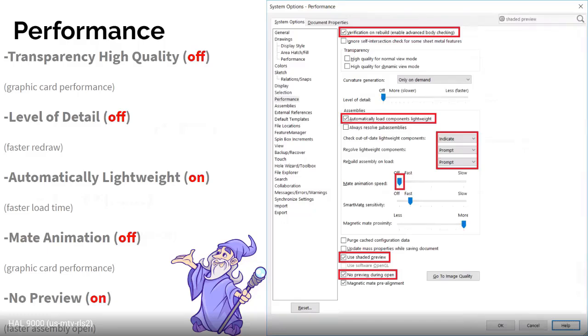SolidWorks is not checking that all the time. And then you could save that part, send it out to somebody. When they go to open it, all of a sudden they get import diagnosis and stuff where there's holes in the assembly. So though it does take a little time for SolidWorks to check the part every time you rebuild, it's worth your sanity and the amount of time if you're looking for what's wrong in a part that it didn't catch in verification. It could take you hours or days of frustration, whereas if you have this turned on, it's going to be a couple of milliseconds every day. But I would have it turned on. The only time I turn that off is when I'm dealing with really complex surfaces.